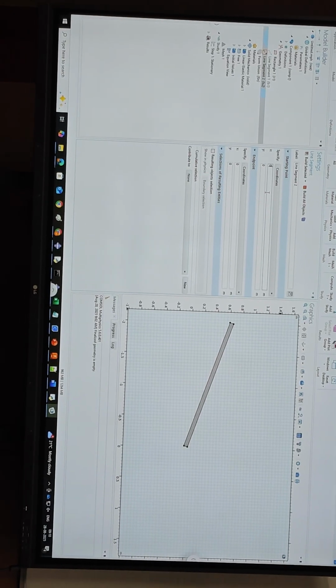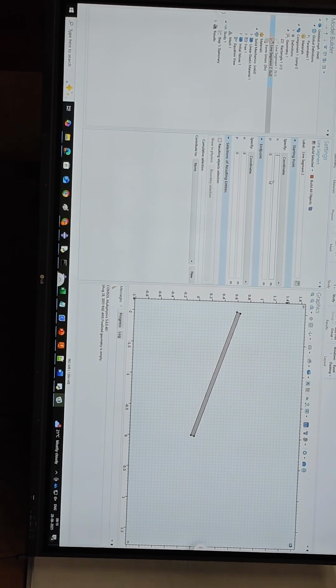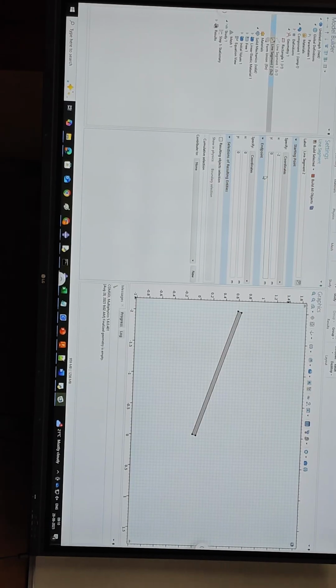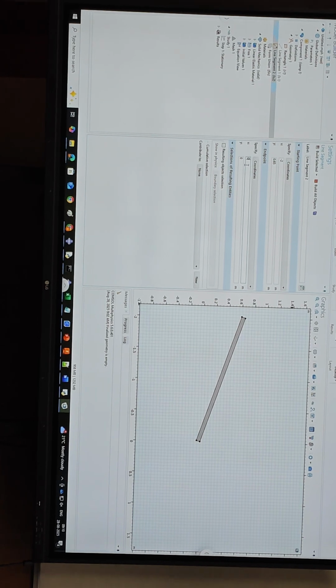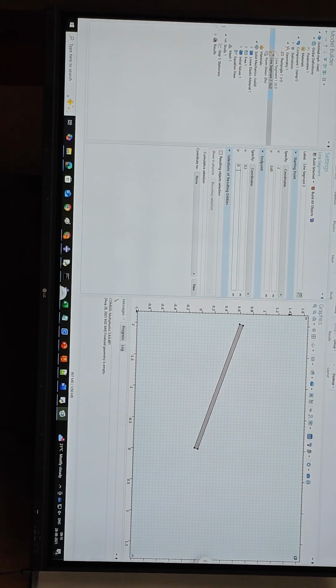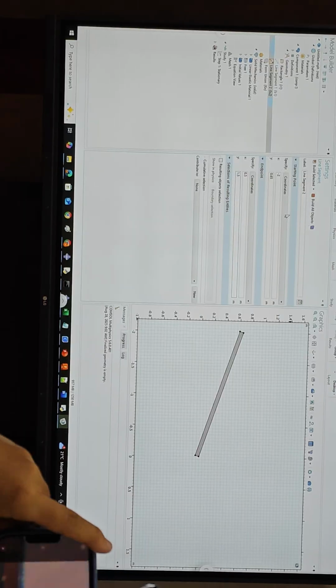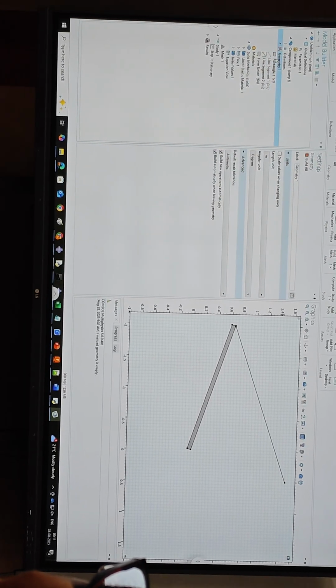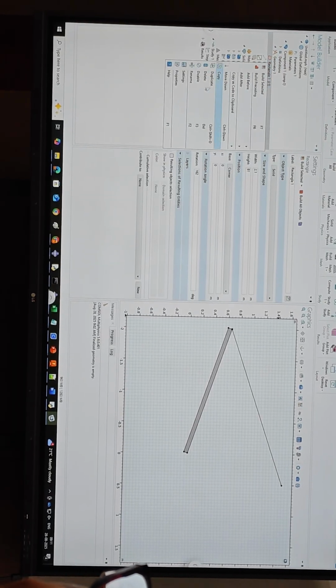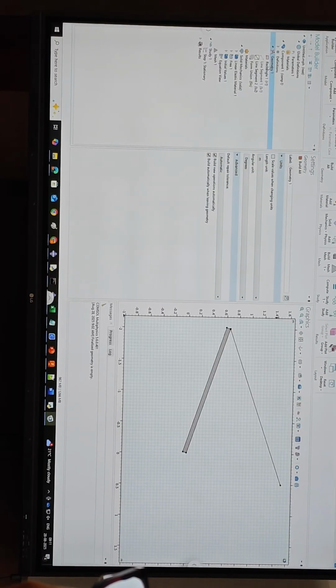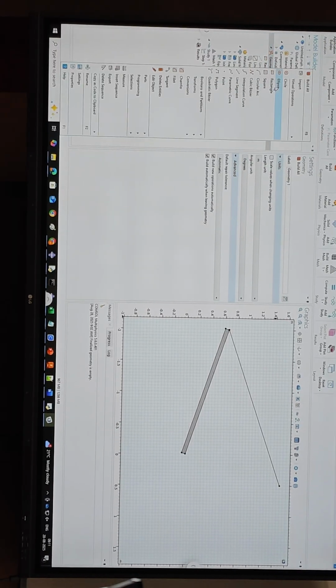So now the next is between -2 and 0.65 to 0.5 and 1.5, right? So that's your next element. So now when I use a rectangle, I'll have to also use, okay, so I can duplicate it. So the one easy way is, once you get good at this, you don't always have to keep going at geometry. You can just right click a rectangle and click duplicate, and you can keep just adding sequentially, but for now I'll just do it the hard way.